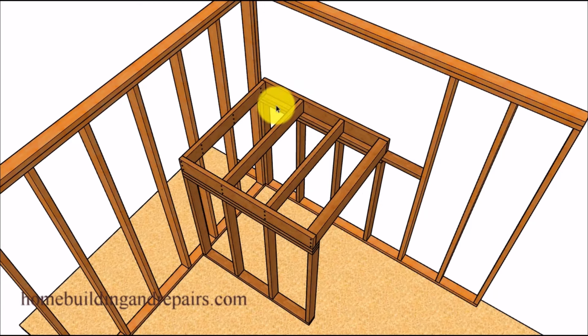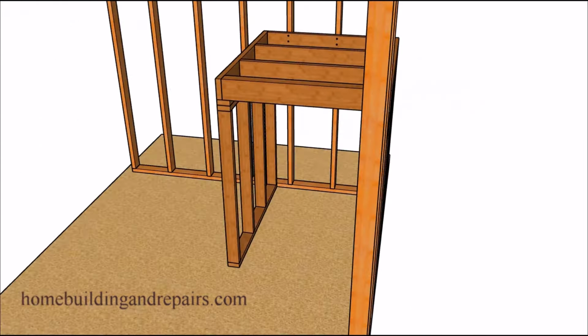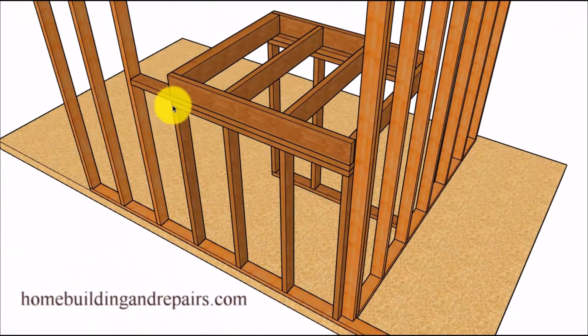And in our last example, we're going to move the wall and put it on top of the framing plate here so that we won't be using as much lumber. And I would strongly suggest to run at least one of the framing plates all the way through to the next stud to give you a little more support to prevent the wall here from leaning either in or out. But again, this is just another option. You don't have to do it.